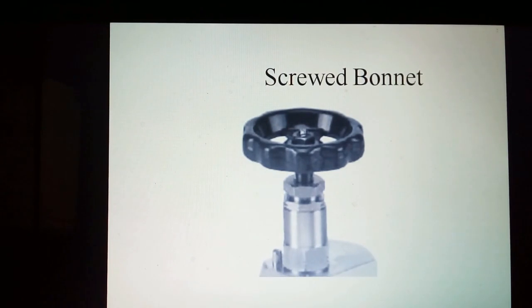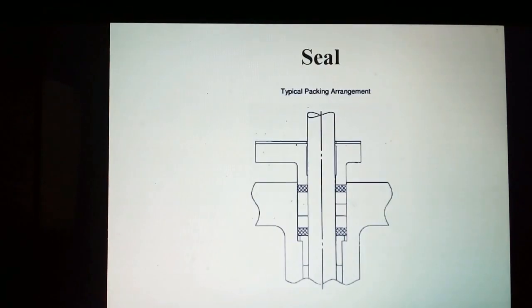The screws on it may occasionally stick and turn when a valve is opened. Although sticking is less of a problem with the union-type bonnet, valves with screw bonnets are best reserved for services presenting no fire hazard or hazard to personnel. The pressure seal is a variation of bolted bonnet used for high-pressure valves, usually combined with OS and Y construction. It makes use of line pressure to tighten and seal an internal metal ring or gasket against the body. The critical factor for valves used for process chemicals is the lubrication of the stem.